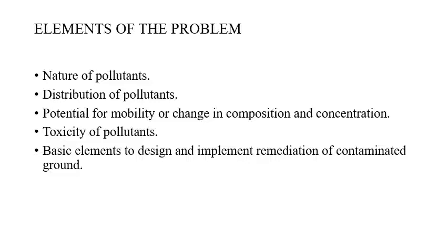So for the same purpose we'll follow the same procedure we do for a normal site subsoil profile analysis. We have different types of tests where we can collect soil samples from various depths, and then we can analyze them. If we want to understand the types of contaminants, then we'll have to do chemical analysis of those soils to understand the types of contaminants present in the soil, right?